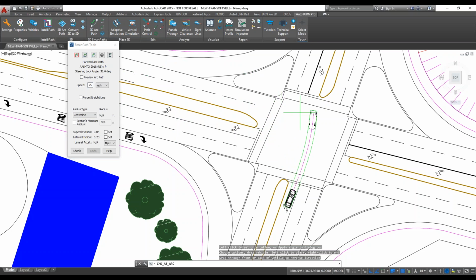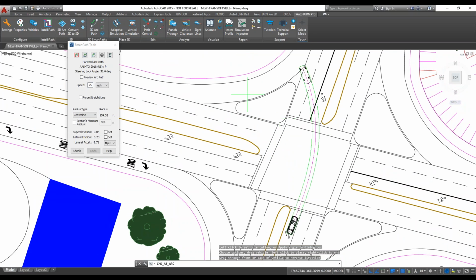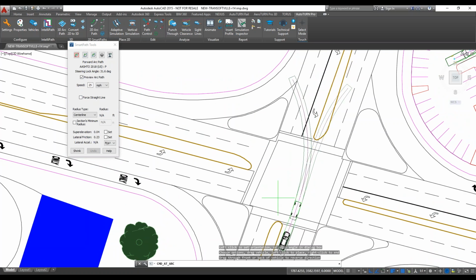And yeah, when we go to 25, you can see there's a big spiral there. If we use the preview paths, we can see it can only turn so tight for this intersection. So we might want to lower it. 25 was way too high. You can see now the changes in the whiskers. We can see based on the current position and the speed how tight we can turn.